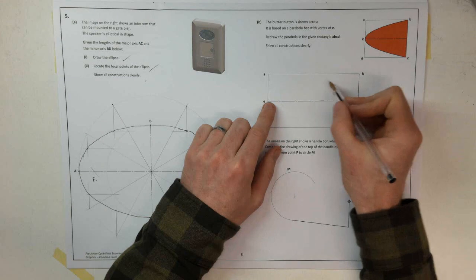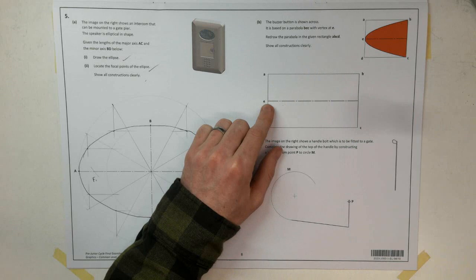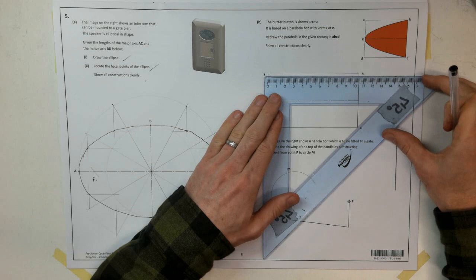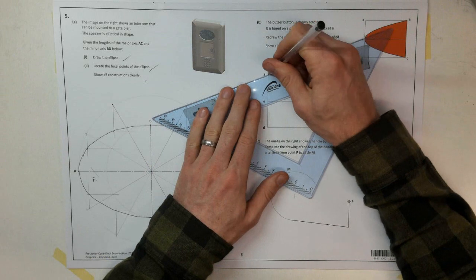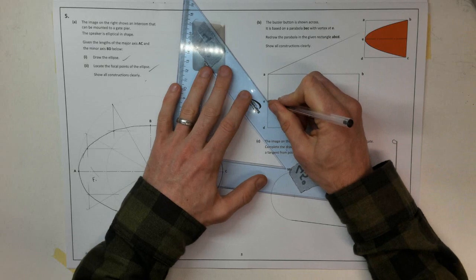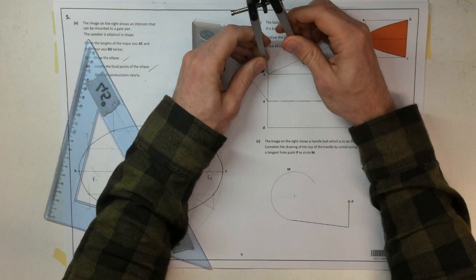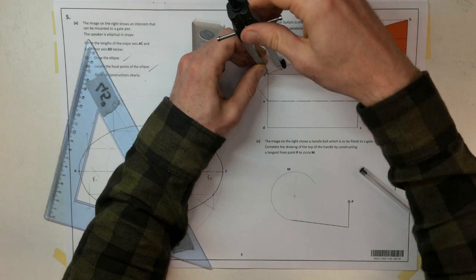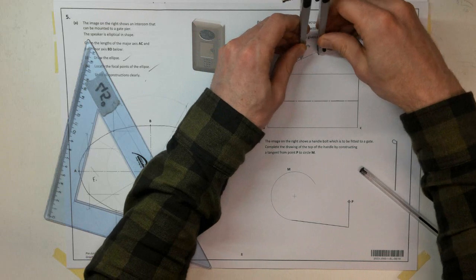We want to show our constructions clearly. So what we're going to do is divide up AC into equal parts, and divide up AB into equal parts. Let me just see, can we measure those? No, not quite. Okay, so we're going to have to use our dividing lines into equal parts construction. So line at any angle, draw a line out, and actually draw one here as well. For AB, let's divide this up into 3 equal parts, will be fine. So 1, 2, 3.